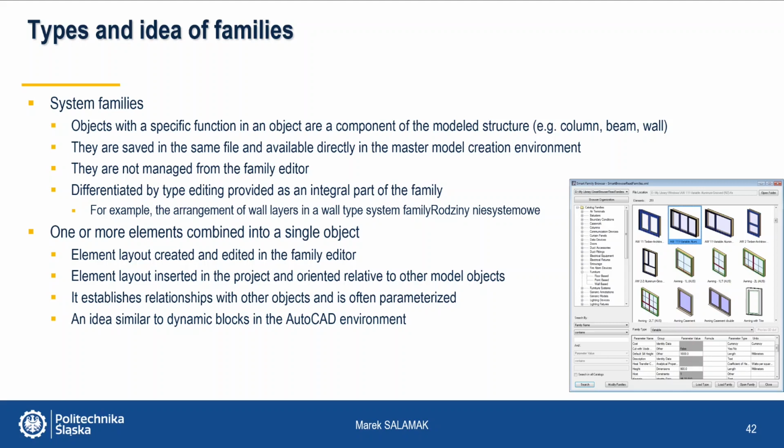Non-systemic families are one or more elements combined into one object. The layout of elements is created and edited in the family editor. After being inserted into the model, it is properly oriented in relation to other objects and establishes relations with them. It is also often parameterized. The idea here is similar to dynamic blocks in the AutoCAD environment.